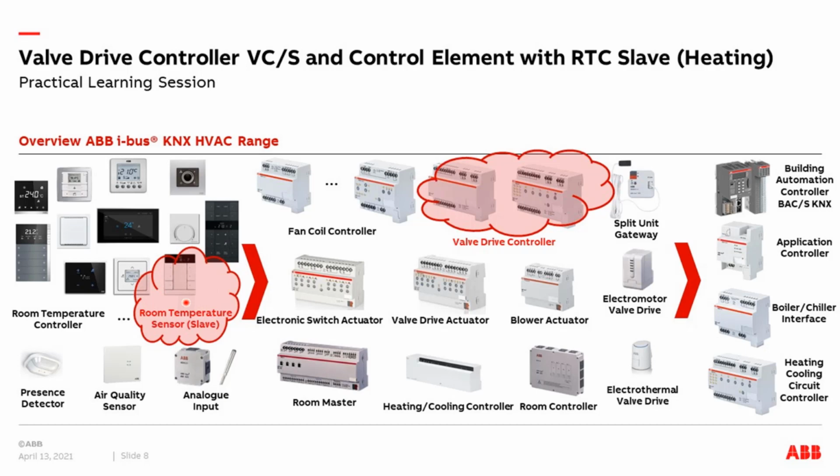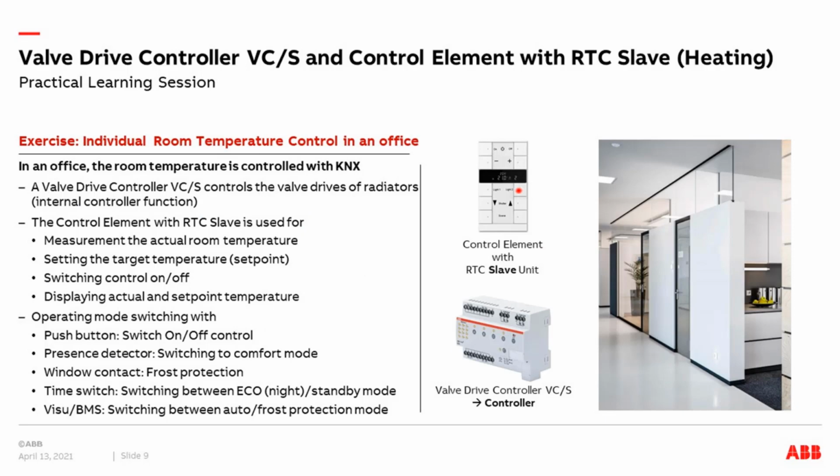So this device measures the temperature and we can set here also the set point. But the controlling is done here in our valve drive controller VCS. So this is exactly the exercise we want to do today. We want to do the individual room temperature control in a typical office.